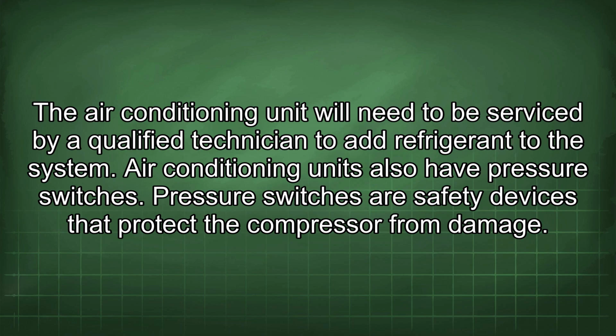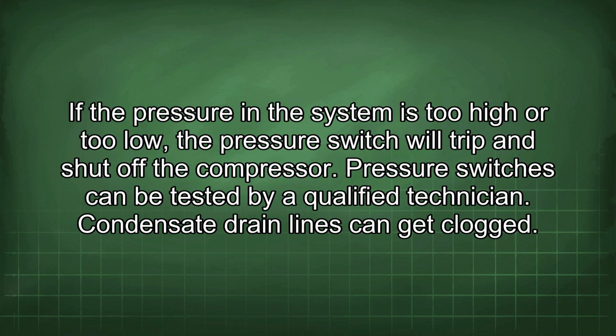Air conditioning units also have pressure switches. Pressure switches are safety devices that protect the compressor from damage. If the pressure in the system is too high or too low, the pressure switch will trip and shut off the compressor. Pressure switches can be tested by a qualified technician.